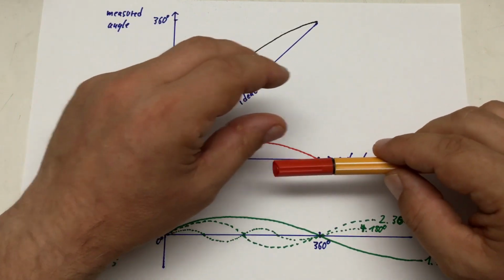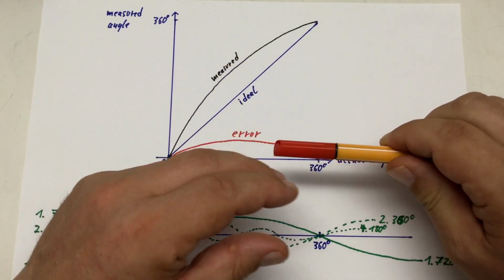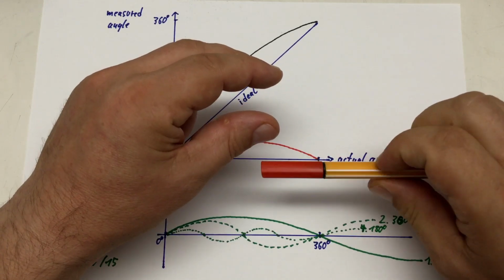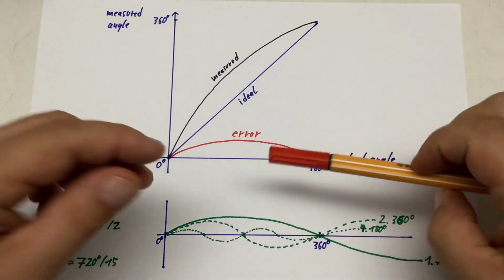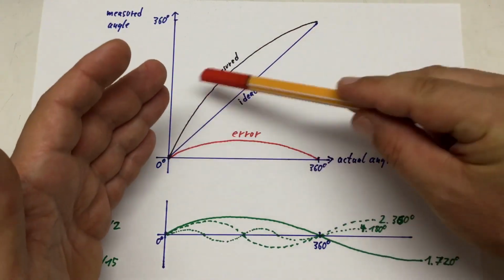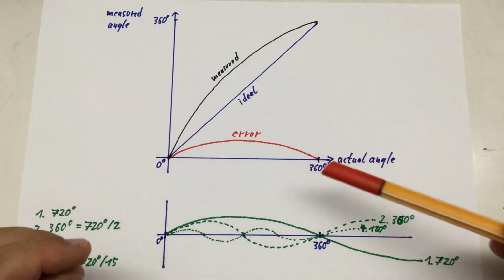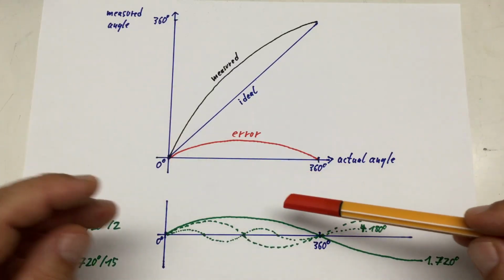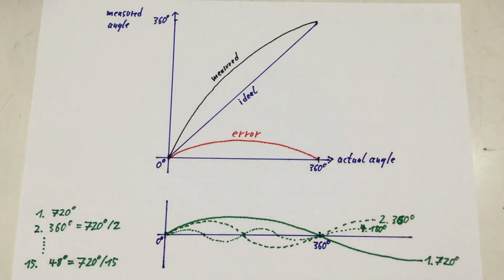That is, the magnet is really beside the sensor, rotating around it, or the sensor is rotating with the magnet in a fixed position. And that produces a whole lot of sinusoidal error signals here. And there's nothing better than a Fourier transformation, or a reverse Fourier transformation, to get these errors out.